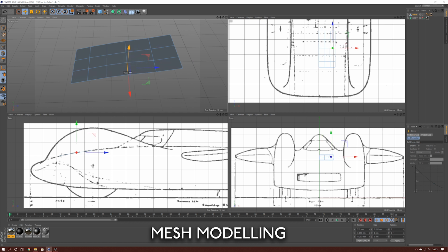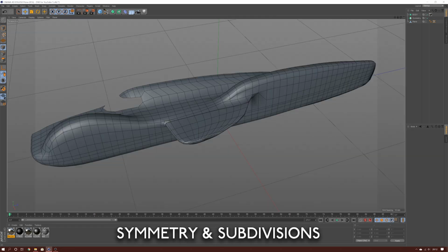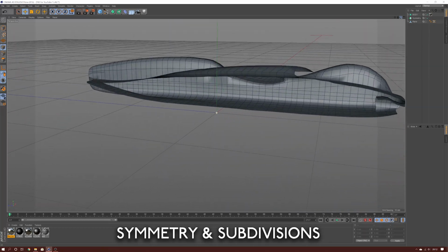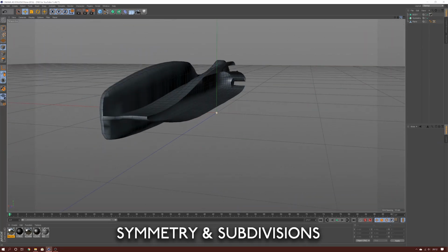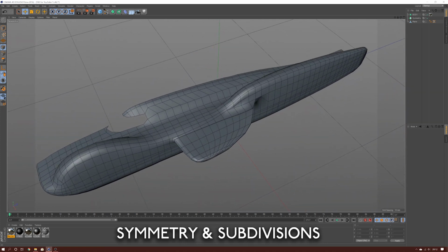By extruding and filling the gaps, we eventually form a mesh, which is a relatively low polygon model. If we were to print the car body like this, it would be heavily faceted. Once you get into this form of modelling, it's actually strangely very relaxing. Anyway, sometime later, this is what you get: half a car. Wherever possible, the mesh is made from 4-sided polygons, known as quadrangles. We don't want to use triangles if we can help it. Triangles are bad. Don't ask, just trust me on this.